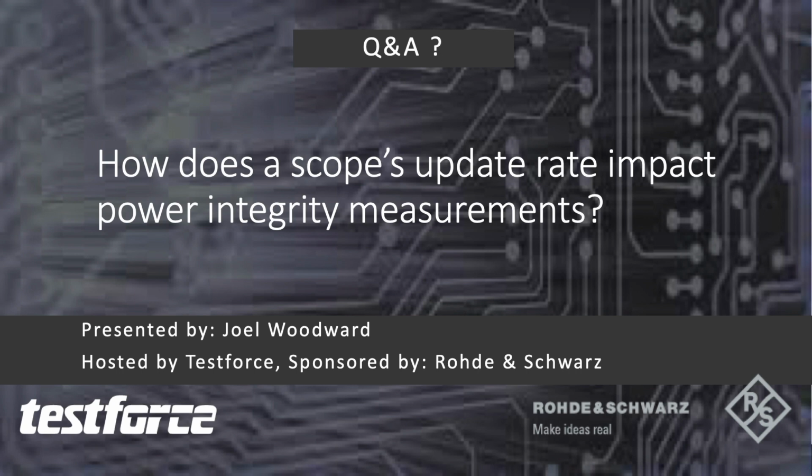But in general, the faster the update rate, the better you'll be able to get statistical convergence on peak-to-peak and noise measurements on an oscilloscope with power rails, and you'll be better equipped to find transients that might be riding on top of the power rail.